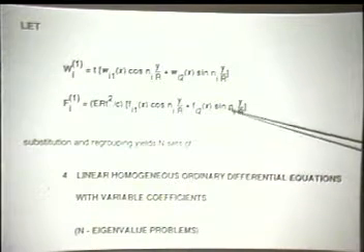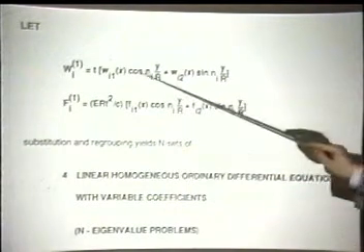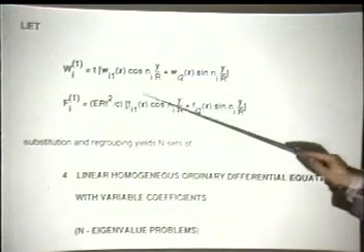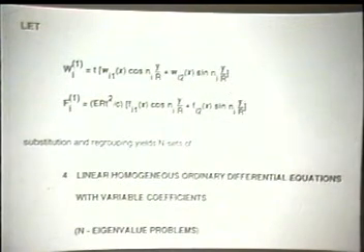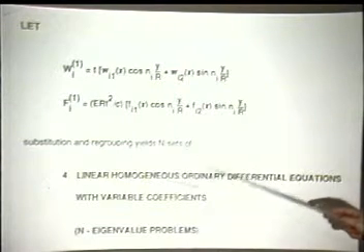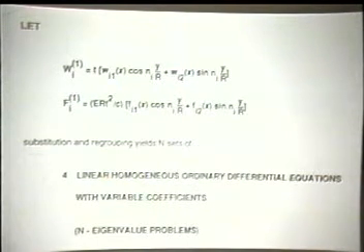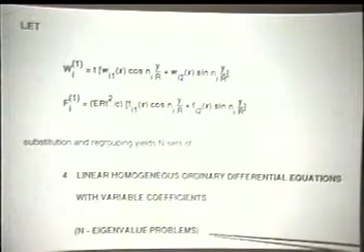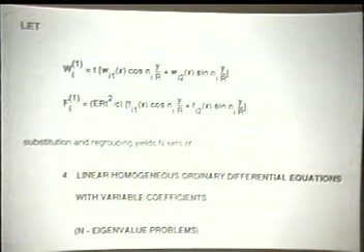And if I take this assumed form, where I now have unknown functions, and substitute them in the previous partial differential equations, those can be reduced to n sets, one set for each eigenvalue, of 4 linear homogeneous ordinary differential equations with variable coefficients. So I have essentially n eigenvalue problems. N is the number of nearly simultaneous modes. The problem is then solved numerically.